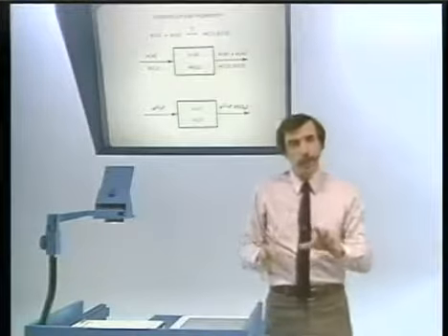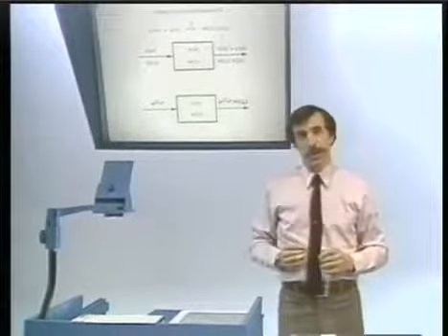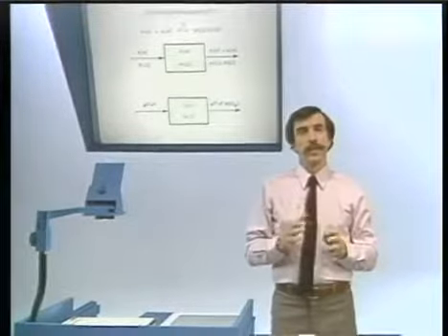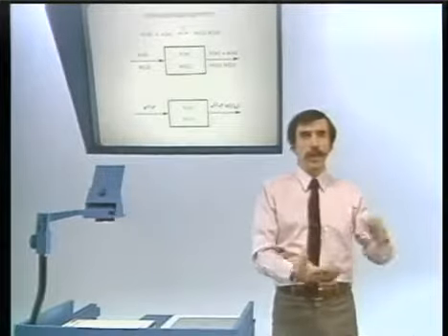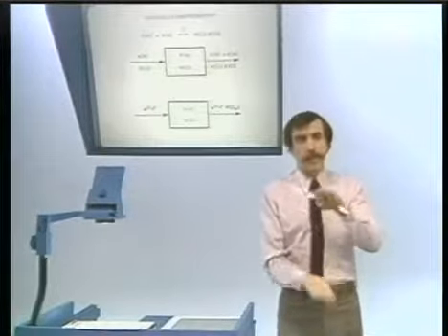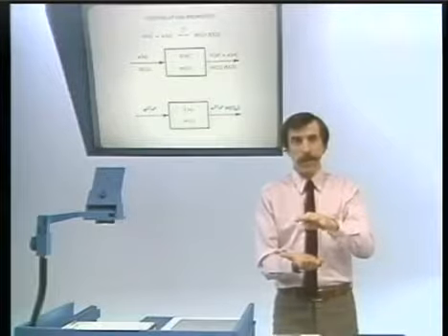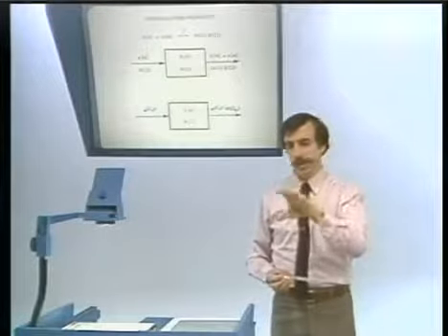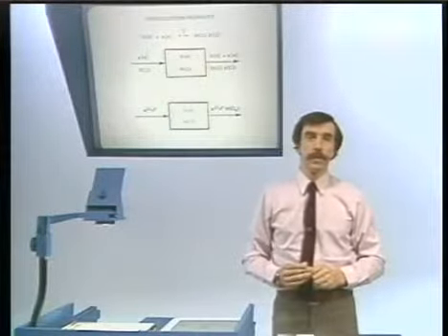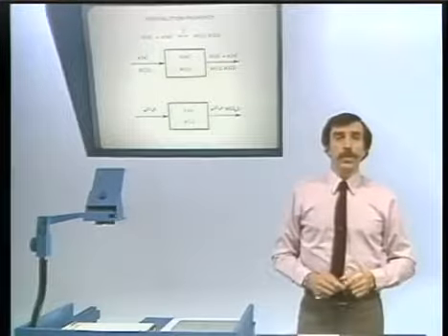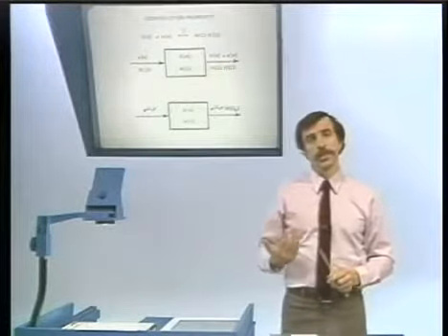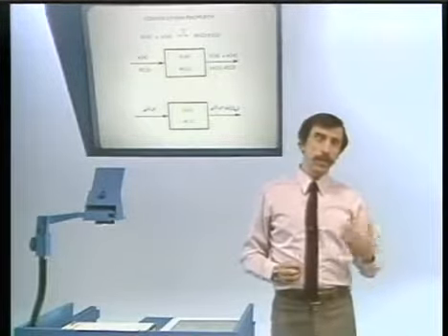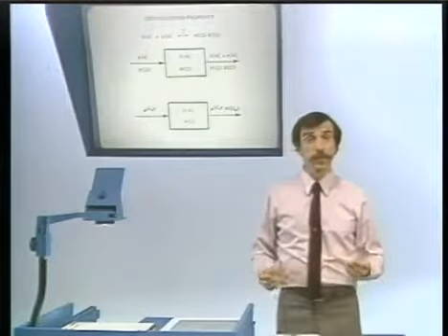So it's important in thinking about the convolution property to think about it in terms of nothing more than the fact that we've decomposed the input and we're now modifying separately, through multiplication, through scaling, the amplitudes of each of the complex exponential components. Now, what we saw in continuous time is that this interpretation and the convolution property led to an important concept, namely the concept of filtering.